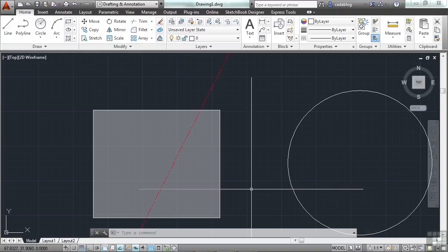So if you put your regular text in and you have a scale of that drawing at, let's say, 1/4 inch to a foot, and then you have another drawing of that same thing with that same text and it's at 1/8 of an inch to a foot, well, you would have to scale the text or put in multiple text objects unless you use the annotation text.